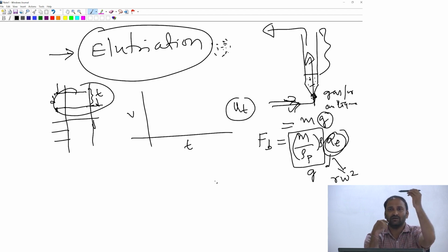Everyone agrees, right? So if I have a cylinder which is falling, the area that is perpendicular to its flow is going to be the rectangle, your length times the diameter. However, if it is falling with its axis in the direction of the external force, again the projected area is going to be the same as the sphere, pi r square. It basically sees a circle, right? So you should be able to develop these equations for particles of other arbitrary shapes, and work out the settling velocity expression.